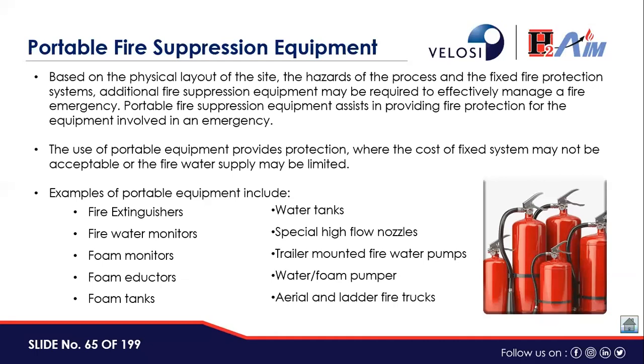So in general, LNG fires are not so dangerous as compared to LPG fires. LPG fires are more dangerous, and for LNG fire, the normal hydrocarbon gas or methane kind of fire protection system is required. Like normal foam system, normal sprinkler system, no specialty as such.